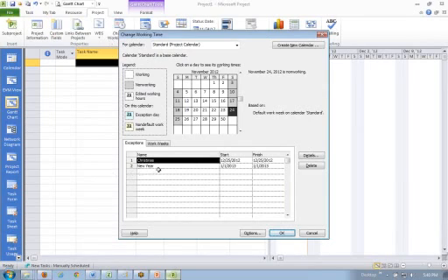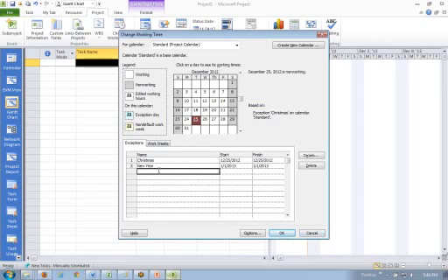In the calendar, basically we set up the holidays, on which days we are not going to work, or the people are not expected to work, or no progress will happen on the project, and any deviation in the normal working days. So suppose a Saturday half day working, or any Thursday or Friday not working kind of thing. That can be changed using the work week. So what we did here is we just set up 2 holidays in this.